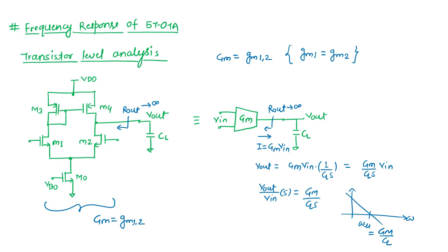Okay. So what we can see, ideally if I'm considering output impedance to be very high, we have simple one pole which is at origin, which is the actual target. This is nothing but an ideal structure or ideal GM cell or ideal op amp where we have no output impedance and we have a proper integrator with the UGB of GM by CL and the gain of infinite.